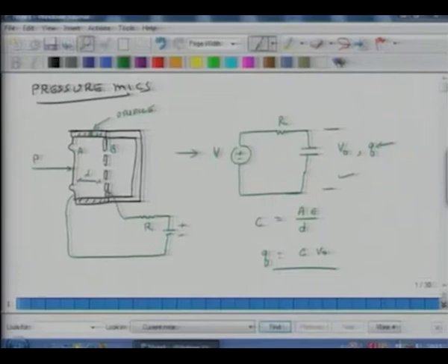As you are developing the acoustic component, bear in mind there's a cavity here, so it has some springiness. There's also a mass of the diaphragm. There's also a stiffness of the diaphragm. So all that has to be taken into account when you develop the entire thing, if you want to.